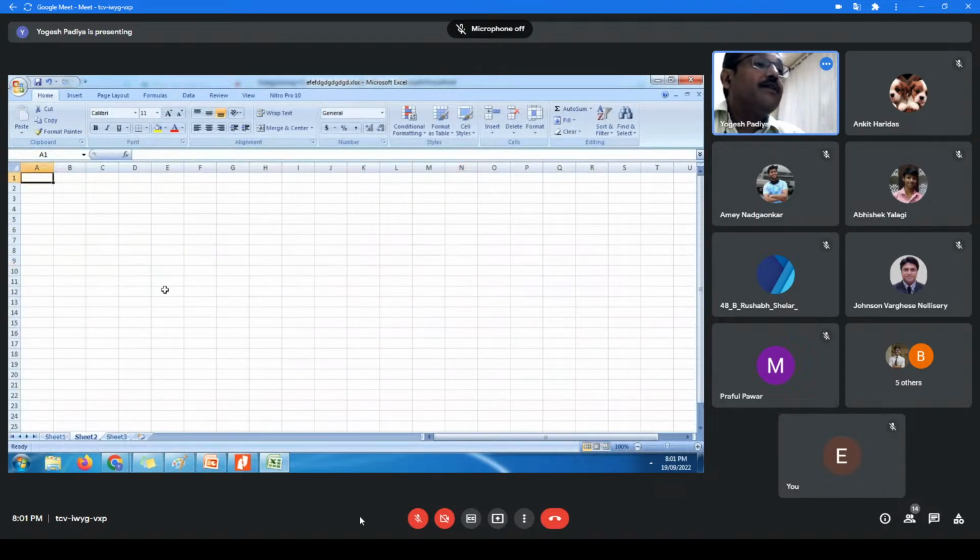Okay. Suppose I have a land having an area of 100 meter square. I can have 1 kilowatt per 10 meter square. It means that I can install a maximum of 10 kilowatt panel.